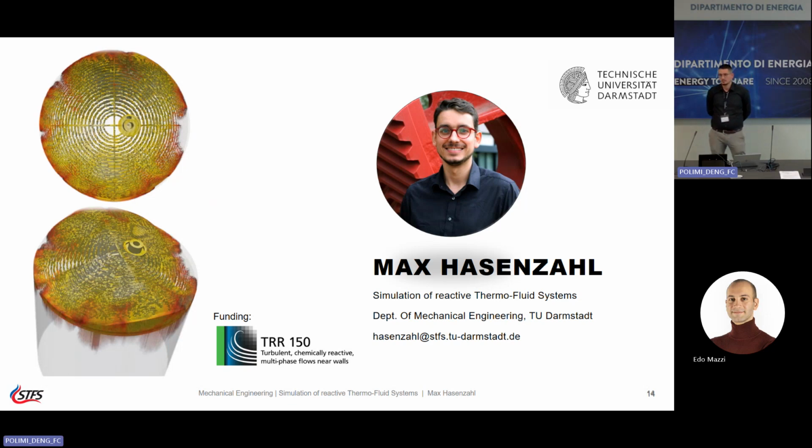So yeah, algebraic wall functions probably. You'd have to find some way to collapse this data to basically a line. I think this is what this community always tries to do. Yeah, I think this will probably be impossible. This kind of thing happens also in turbomachinery. You have a flow which is impinging on the blade, so you have attachment lines and separation lines on the surface of the blade. So detachment with reattachment. So the nature of the profile normal to the blade is very chaotic. I think there is no chance to have a unique wall function that can match all the possibilities. Yeah, no, I totally agree.